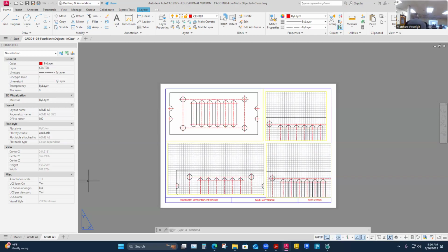The other thing you will probably end up doing is hitting multiple. Now you did one, it only lets you do one, but do that again. Go into the fillet command again. The radius should be the preloaded one you just did, so it's 3. Hit enter on that, and then hit M for multiple. Then hit enter, and now you should be able to click all around this thing and never get out of it. I don't like that multiple is not more intuitive. You have to keep going through this.